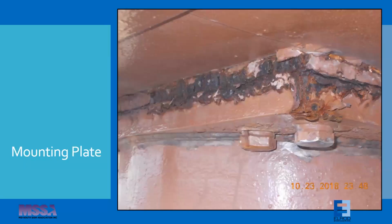Moving down the sign, this is the mounting plate. This is an example of material degradation of the mounting plate. We caught it early enough that the solution to this would be simply to grind down to bare metal, coat with a rust prevention such as POR-15, and then repaint.